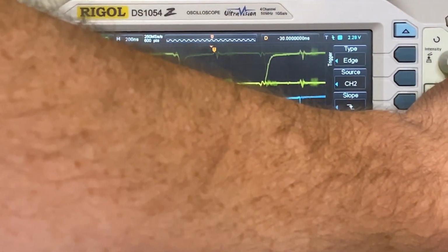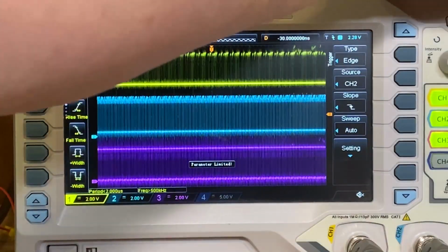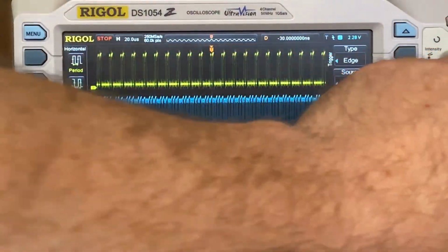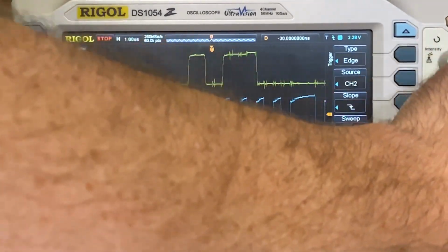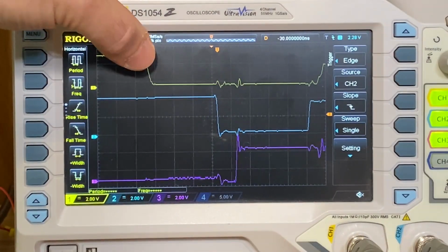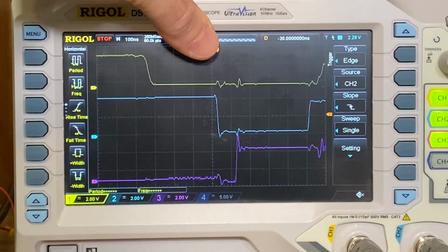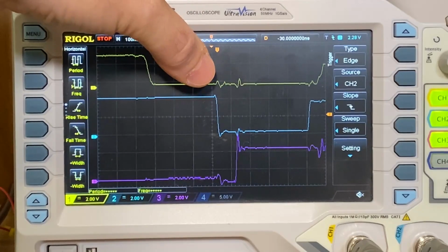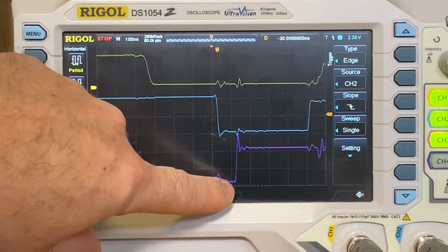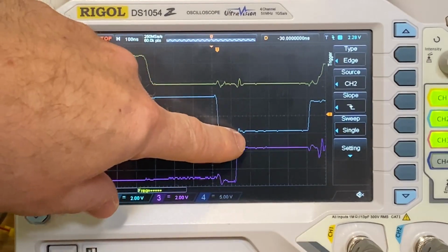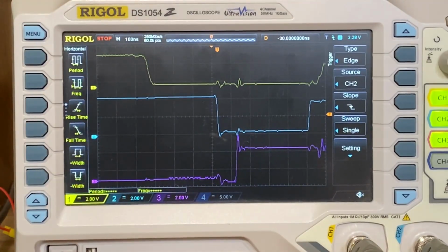So if we take a snapshot, we can actually look at one of these traces in detail. Here we can see the address line going low, and then about 350 nanoseconds later the chip select line gets driven low, and these are 100 nanosecond divisions. Within 100 nanoseconds the Software Defined Retro ROM is driving the data bit high. Presumably that's right, the VIC-20 is running, it's not crashing.